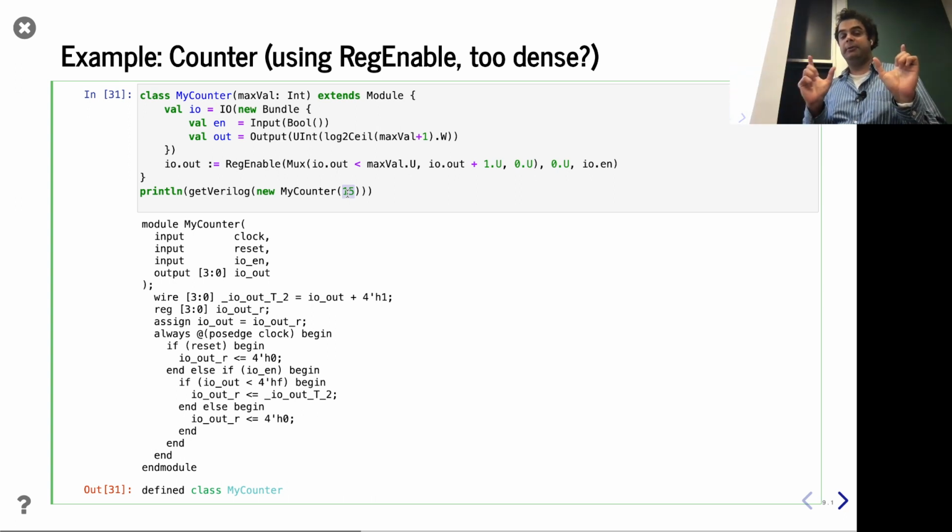I want to be really clear about our terminology here. I'm saying the maximum value the counter holds, right? Because remember, technically 0 is also a value the counter holds. So if I have n as my maximum value the counter holds, really I'm counting n plus 1 things, right? Because there's zeros through n. And so, okay, I need to have enough bits to hold that value.